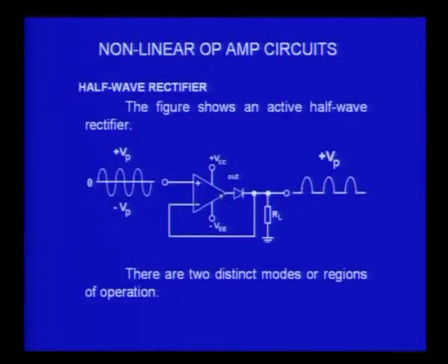So, it is an open loop condition. When the voltage increases here, this voltage will have to be amplified by the open loop gain of the operational amplifier, and we know the open loop gain of the operational amplifier is 10^5. So, whatever is the voltage here will be multiplied by 10^5, and that will be the voltage appearing at the output terminal of the operational amplifier.